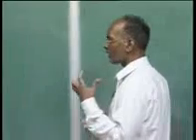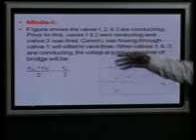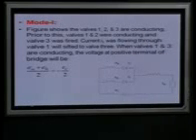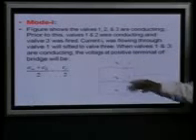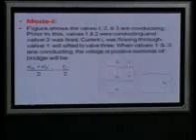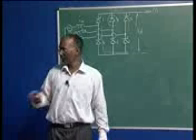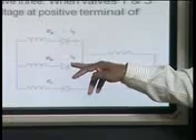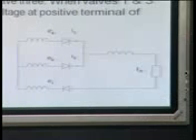Okay. Now, let us go for analysis when valve 2 and valve 3 are conducting, means now mode 1, where we are taking either 2 valves conducting or 3 valves conducting in a repeated manner. So, this figure shows that valves 1, 2 and 3 are conducting. You can see 1, 3 and here 2 are conducting, means before, 1 and 2 were conducting, and 3 got the pulse and it is now fired. However, the current shift from 1 to 3 is taking some time, and that is U degree, and we are assuming that this U degree is less than 60 degree.